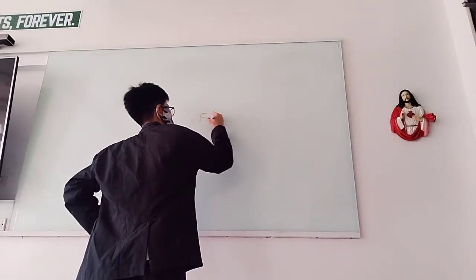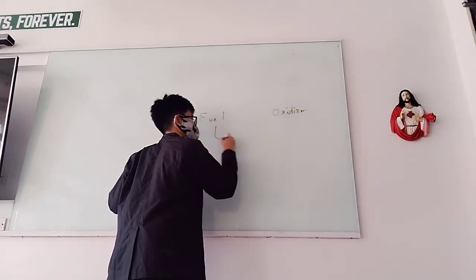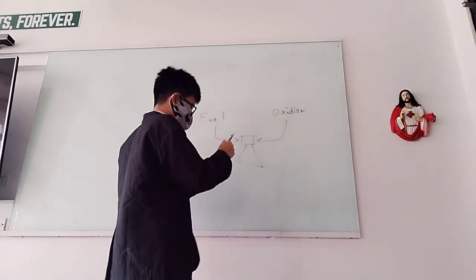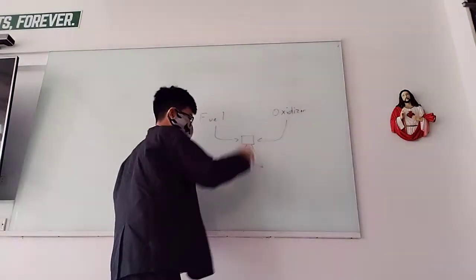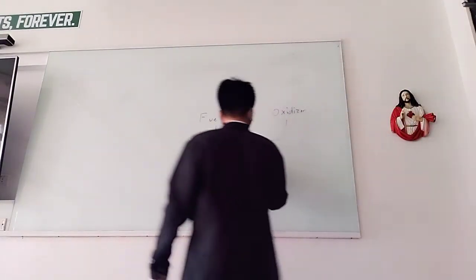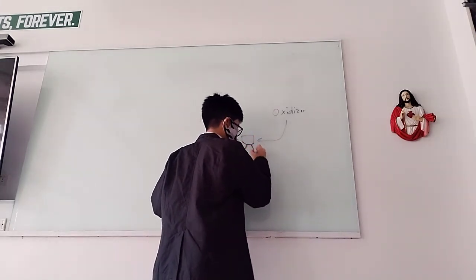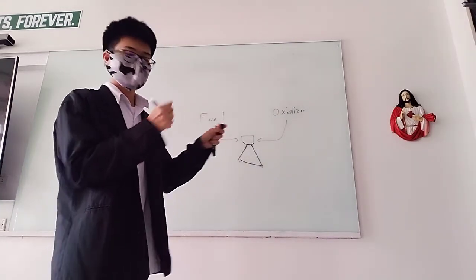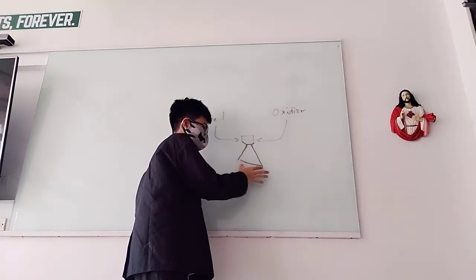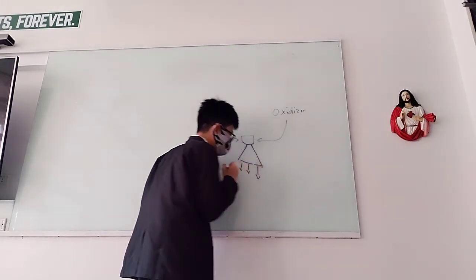So you have a fuel, and you have an oxidizer, and you direct them into a combustion chamber, and then you burn them, or make them explode, or mostly burn though, and then it produces thrust. The nozzle here directs the thrust in one direction, and most engine shapes are actually like this. So they have the combustion chamber and then they sort of choke it, and that's to amplify the exhaust velocity. So the hot gas that's going down here, the tangent vectors at this point, would give us the exhaust velocity.